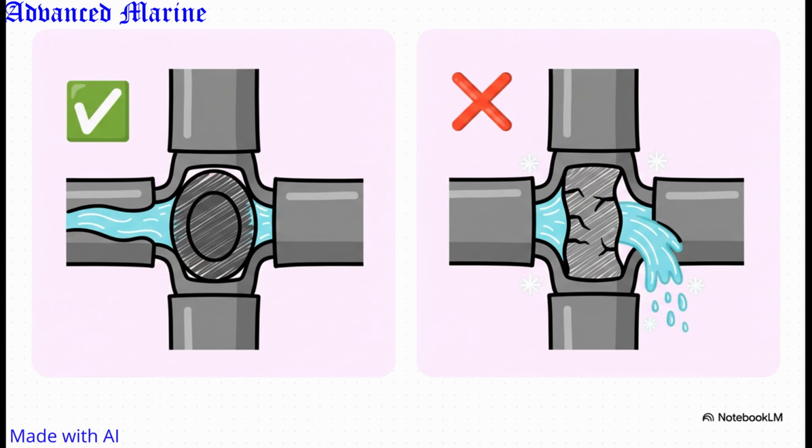On the recommended side, we have our reliable defenders. Teflon and graphite are universally excellent. Certain elastomers are also found within strict temperature ranges, like neoprene between -40 and 80 degrees Celsius and butyl between -54 and 149 degrees Celsius.